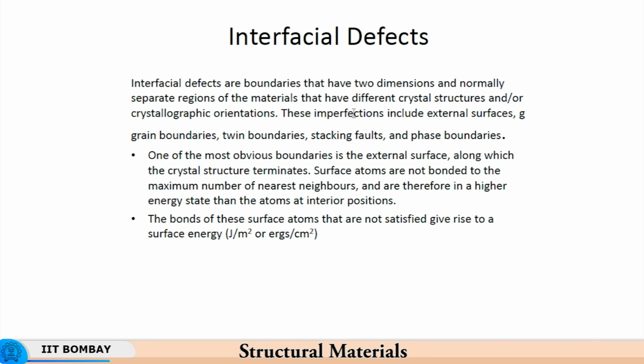Cementite is a product of a chemical reaction between iron and carbon. So Fe3C, iron carbide, is the chemical formula for it, and the nature of this iron carbide is different from the body centered cubic structure of iron dissolving some amount of carbon.